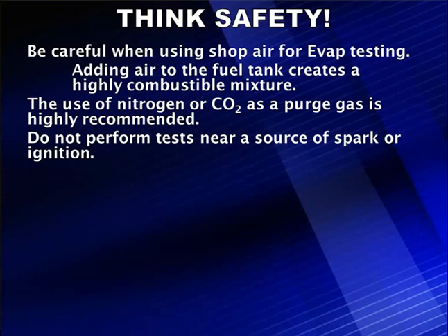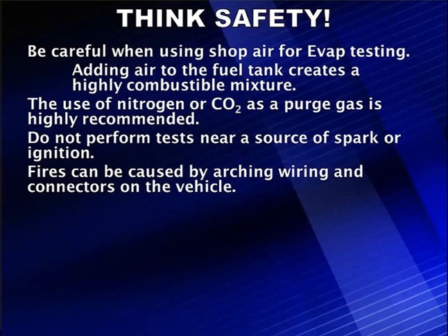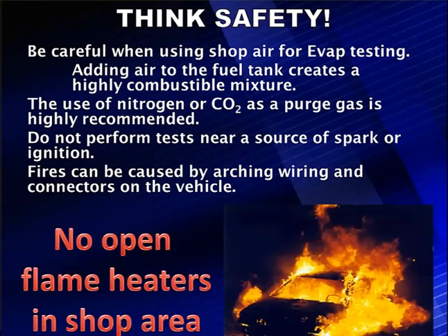Do not perform these tests near an open source of flame or spark. And remember, fires can be caused by arcing wires and connectors on the vehicle. And for God's sake, don't use open heaters in the shop like a torpedo heater in the wintertime, because you've got the shop closed up and you can have a fire. Go on the internet, see how many fires are caused by Evap systems putting out so much vapor it catches things on fire.